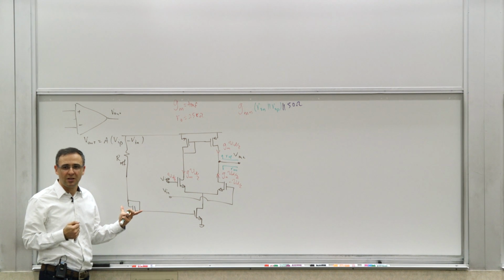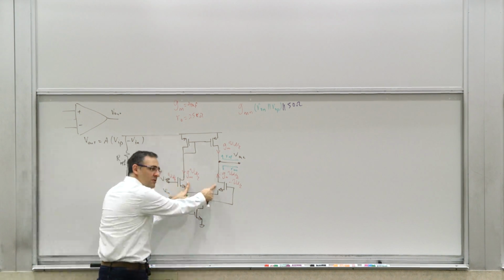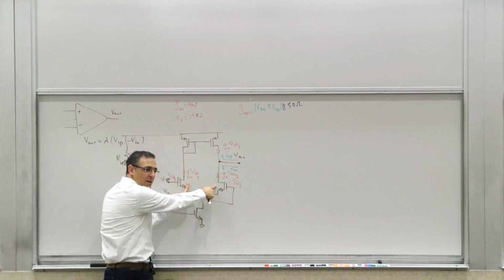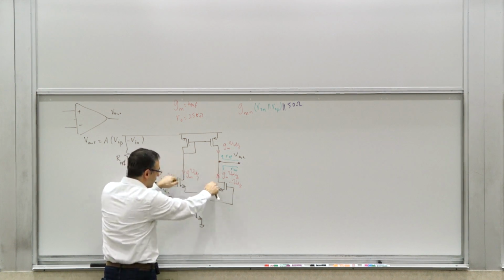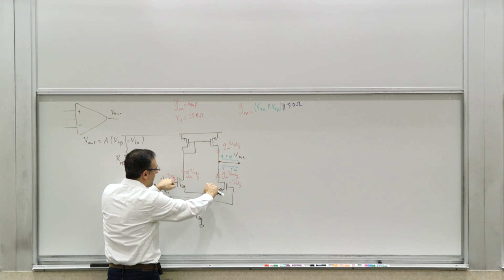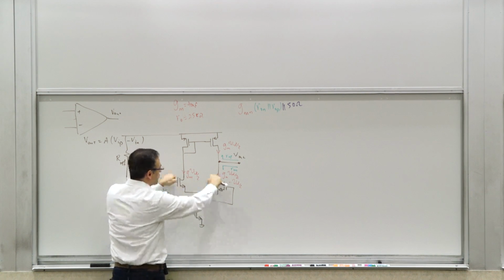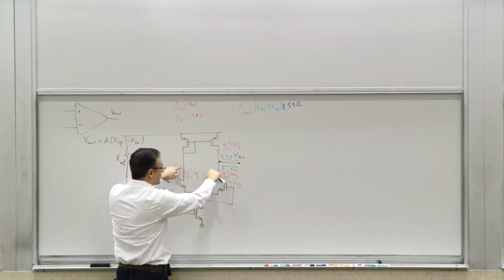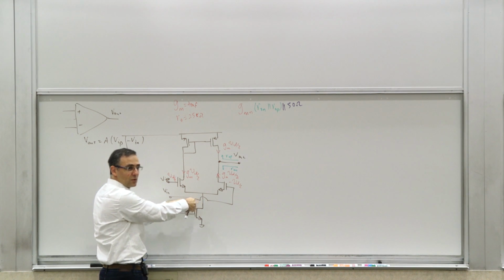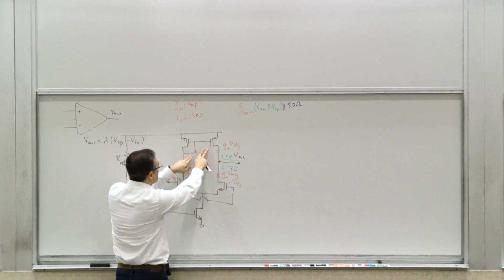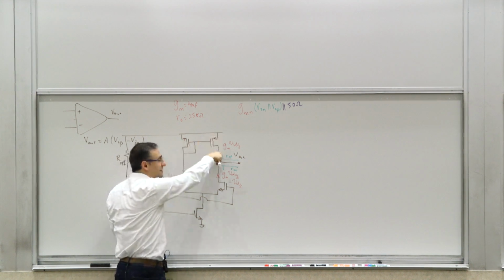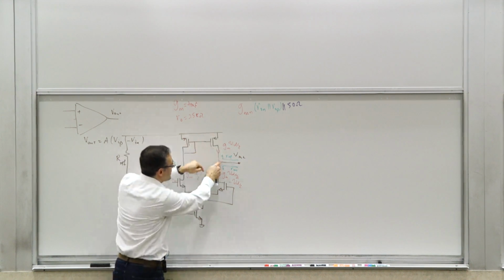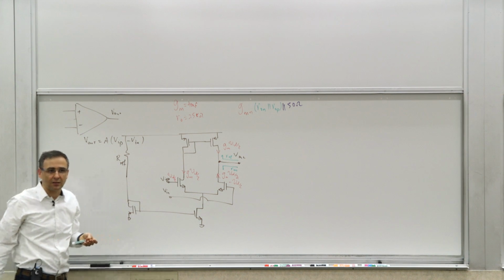Right? What do these two guys do? It's a differential pair, right? It converts the differential input voltage to a differential current. If you apply common mode, if this current source is a good current source, that output voltage common mode is not going to change because the sum of them are forced to be constant, right? What do these two do? It takes one of those currents, reflects it here, copies it here, so you can actually combine them into one node and you get a single-ended conversion.